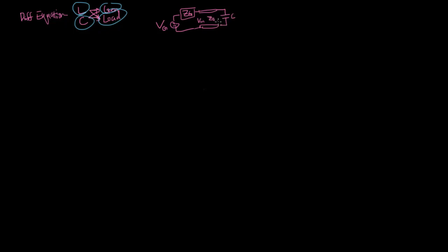And so the side of the transmission line with the reactive load in question, we'll call the junction. So this will be the voltage at the junction, VJ, and we'll have the current at the junction, IJ. In this case, VJ is what we've been referring to as Vout.